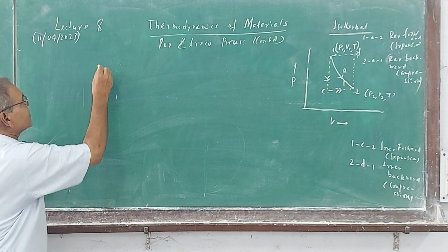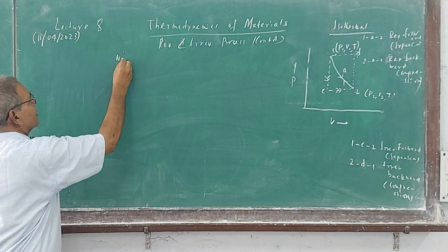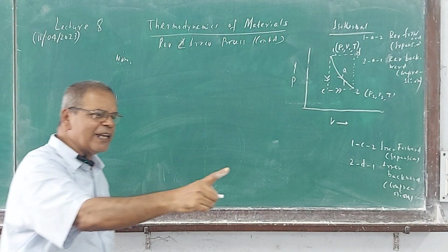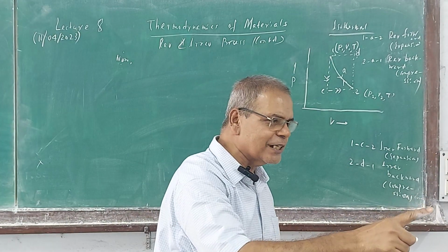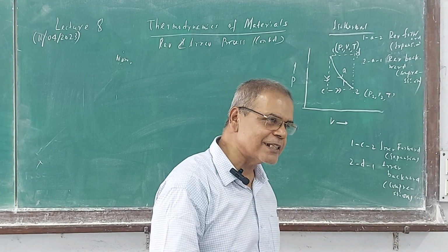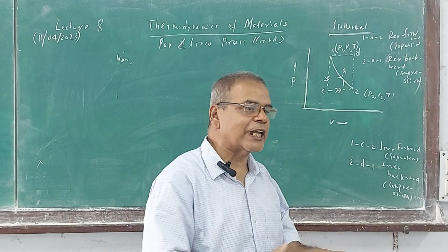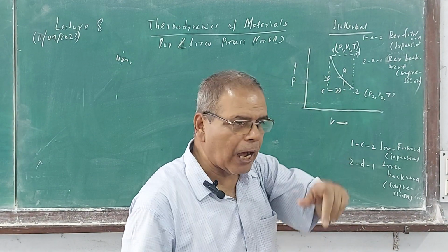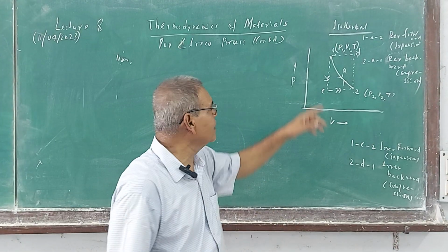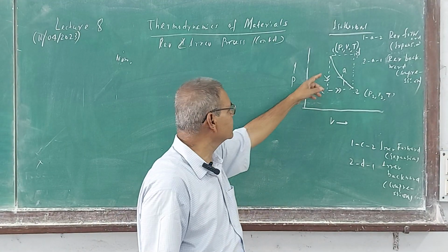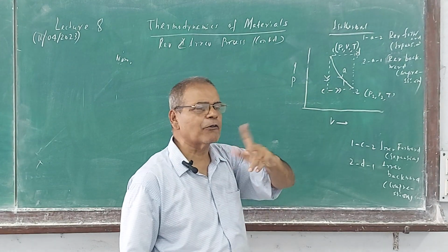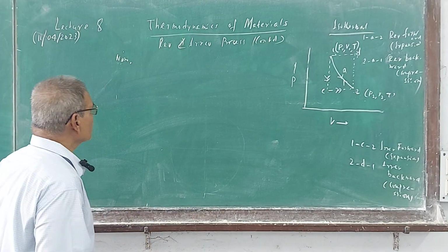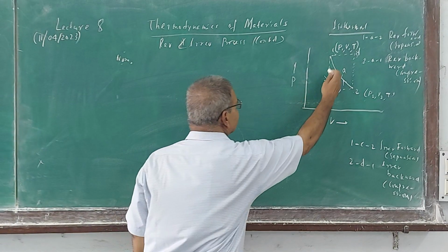Now take up the next topic. I think you have understood this. Any difficulties? Easy, one line answer. Why can the irreversible process not be reversed? In totality, meaning both system and surrounding. The system can be, but the surrounding cannot be. How will you justify this? The forward path and backward path will not be a perfect backtrack. They will be different curves. One is below, another is above the reversible path.